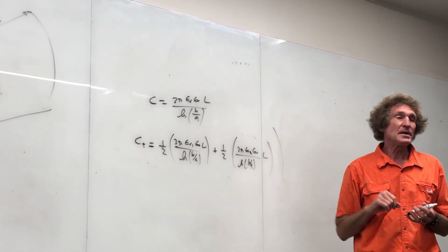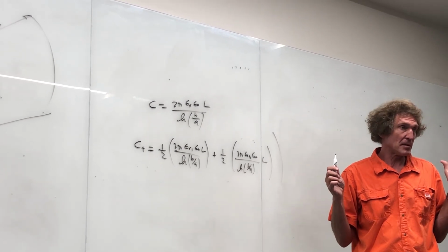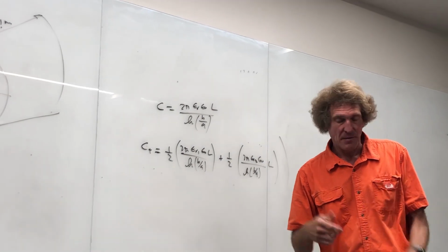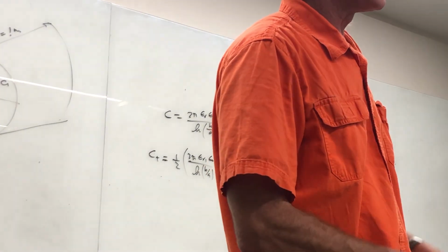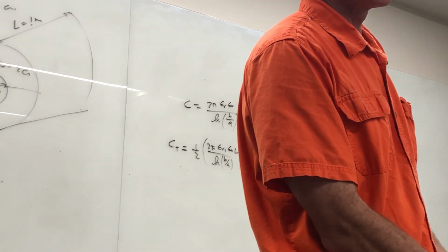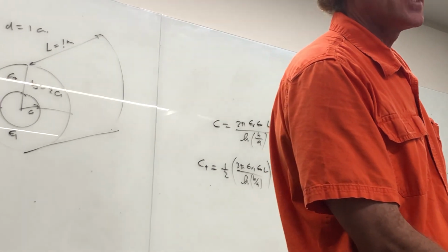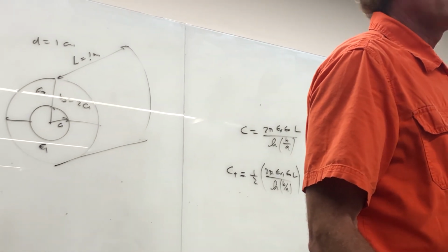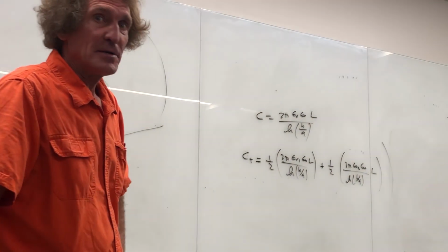I could make it 3 different dielectrics, all with an equal amount of plate area, right? And then it would be 1/3, 1/3, 1/3 times the capacitance as if the whole thing was filled with only one dielectric, right? All right, I'm throwing that one out. That's not a bad problem. Anything else? Think of that with resistance too, right? It would be resistance in parallel, right? Anything else?